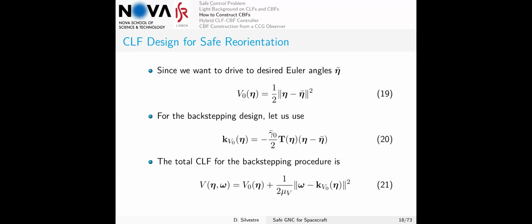And then for the backstepping, that's where the provocation comes back to bite me, because in the end we still need a nominal control, and you can use anything that is Lyapunov based. Here, as you can see, we denoted this controller V0 because it's just for the upper part, so it's just for the angles. It's assuming that you can control the angular velocity directly, and it's just for that part, because everything that comes below that is backstepping.